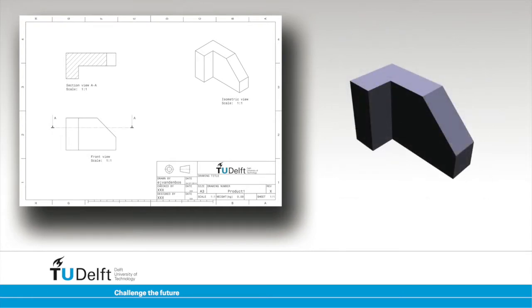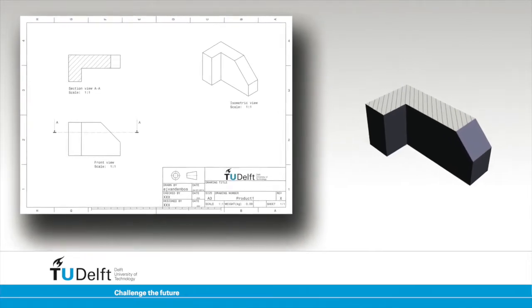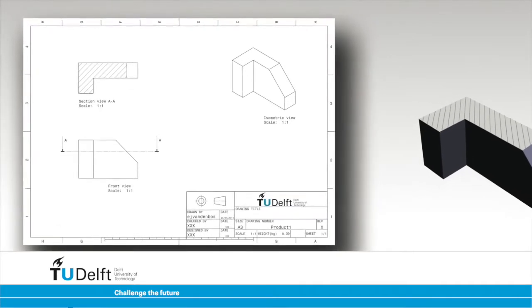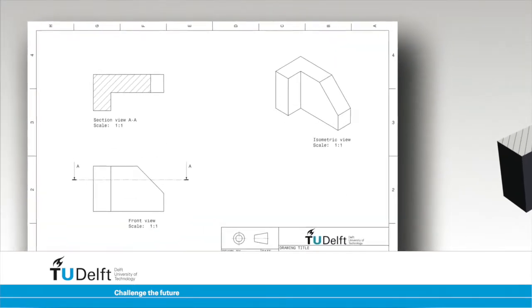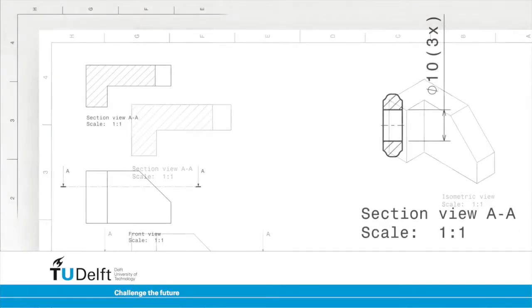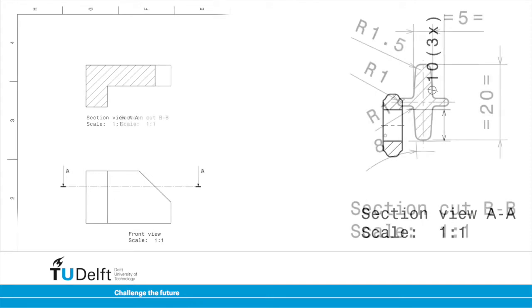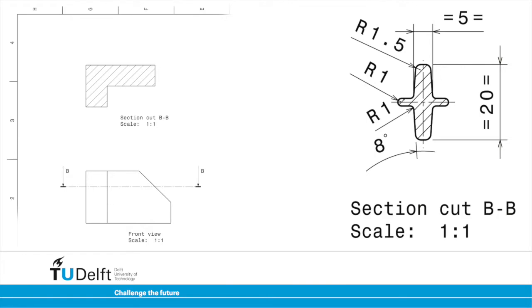An engineer has the option to show or not to show the geometry of the object being drawn in the background. In the example, a small portion of the object is shown to the right of the hatched area. This represents the remaining slanted face, so in this case, the background is shown. The background is shown by default, unless it reduces the communicative value of the section. In CATIA, the 3D application with which you will be working later during this course, sections showing the object's background are called section views. Sections where no background is shown are called section cuts.